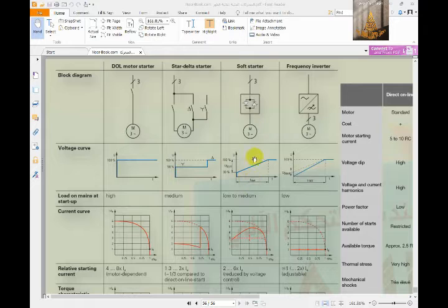And for the soft starter, it starts from 13 percent, maybe 14, maybe more, maybe less. You just control on the soft starter how to set this minimum voltage when you start, and it softly starts to reach 100% of the voltage curve, but not starting from zero. You have to note this part is very important.